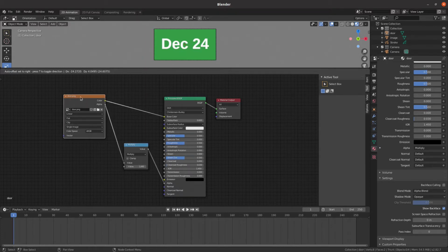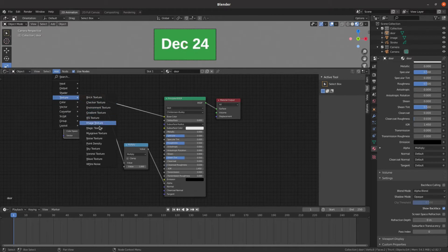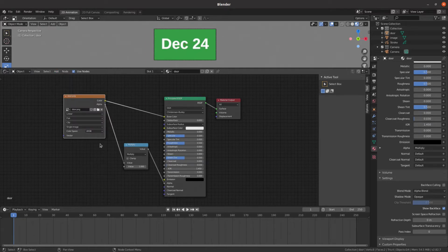But what we wanted to do is to add a texture to it. Now there are some textures in here, so if you wanted to make it a brick effect or various different effects in there, you can use those, but they don't give us the granular control that we need here, which is why I created that texture, the reveal.png, which is just a grayscale image.